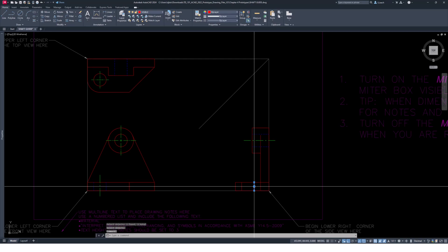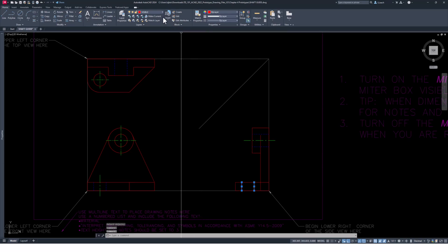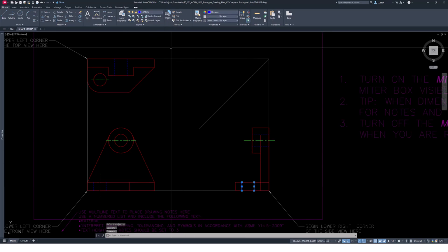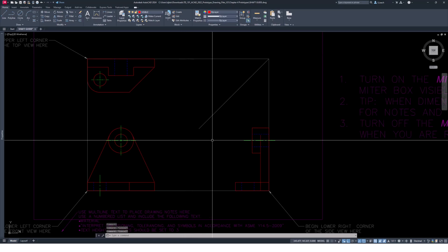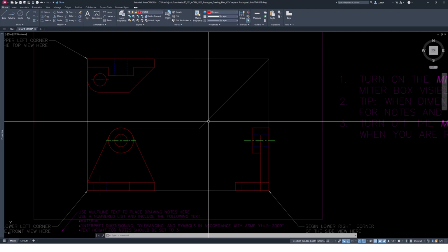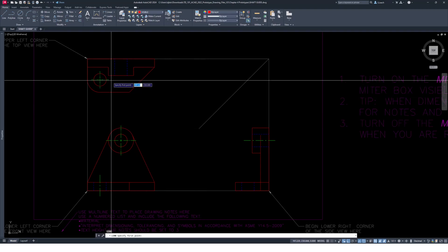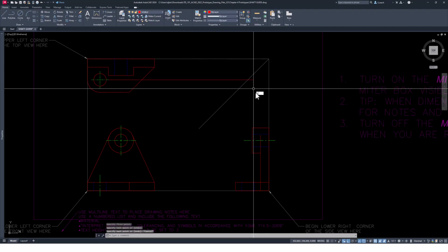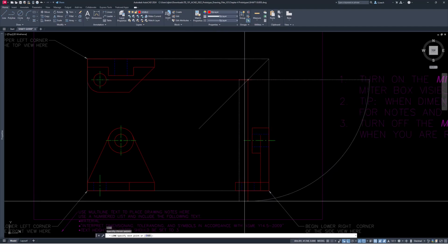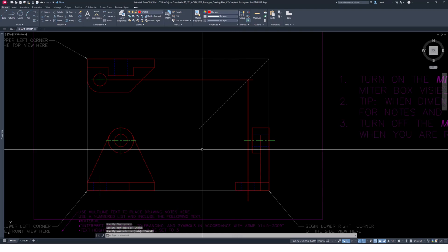So these two lines are going to be hidden lines. Can I copy that over? No, I can't, because those are different sizes. All right, so I'm going to project this over, project it down. That tells me where the center of that is. Now I can actually copy.